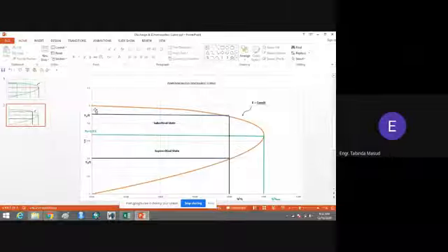It's very simple. You have the value of y1 divided by e, so from y1 divided by e you will draw a line towards the upper limb of the curve, then you will come down to touch the lower limb, and then you will extend your line towards the left side, towards the y-axis, and you will get the value of y2 divided by e.